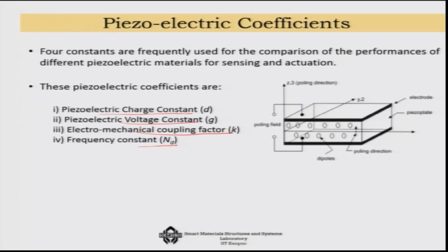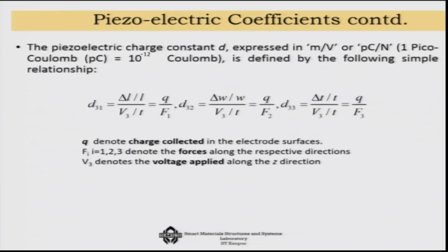When we discuss them, keep in mind that the planar part is represented by x, 1 and y, 2. That is the planar part, and the transverse direction we represent by z or 3, which is also the poling direction. With this axis system in mind, let us look into the piezoelectric coefficients.